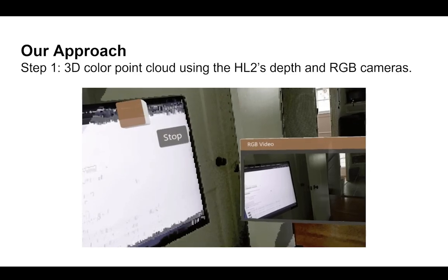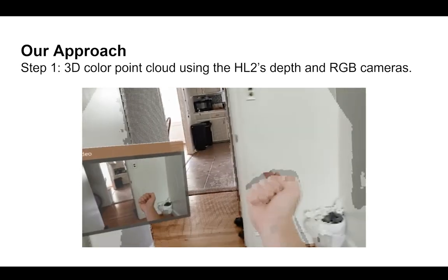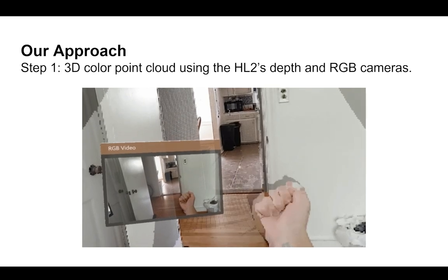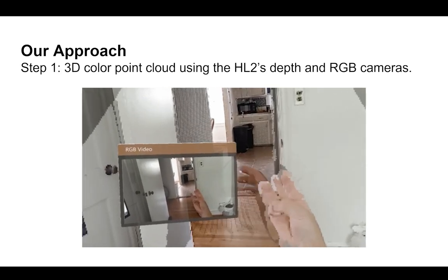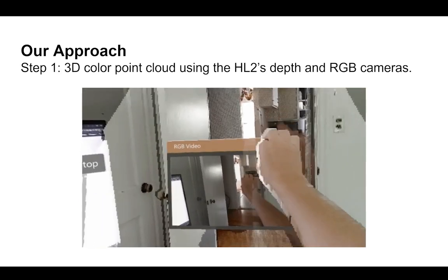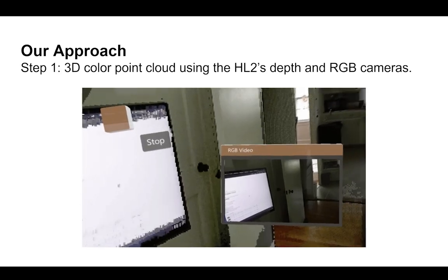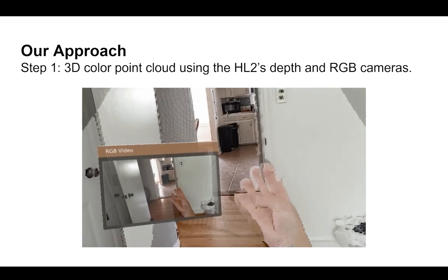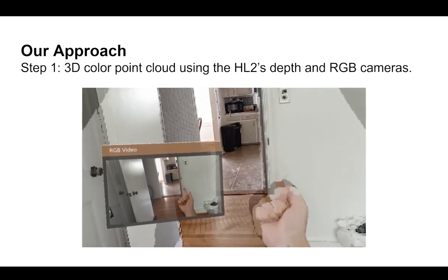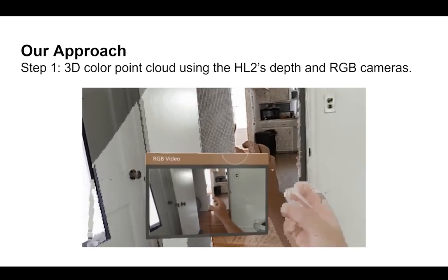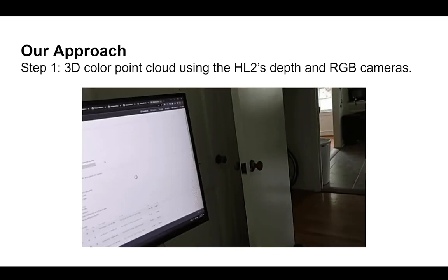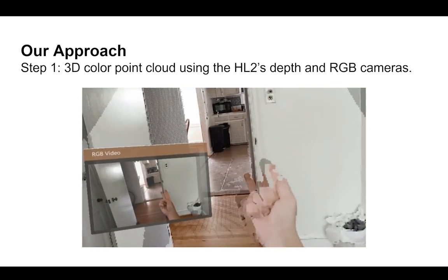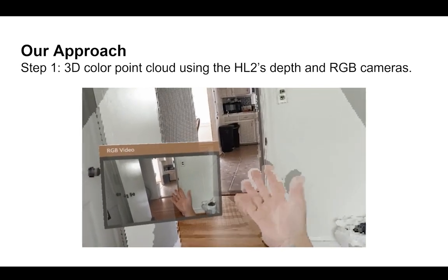Our first step toward obtaining 360-degree images is creating a color point cloud using the Microsoft HoloLens 2. This augmented reality device has a normal RGB camera like you use with a phone, as well as a time-of-flight depth sensing camera, which allow us to create a virtual rendering as if it appears directly aligned to the real world. These cameras run on separate threads, so we temporally and spatially synchronize the two streams together into a real-time point cloud rendering.